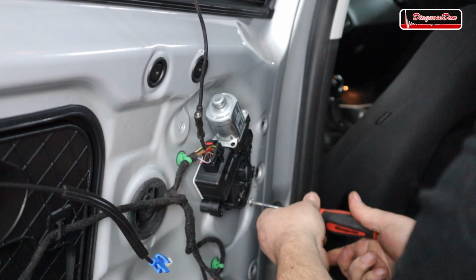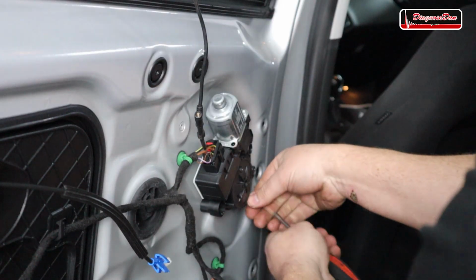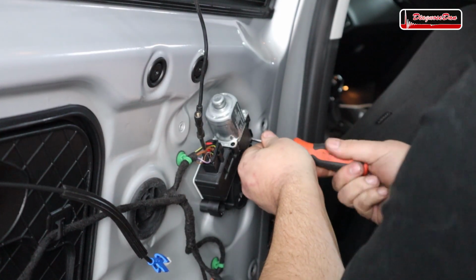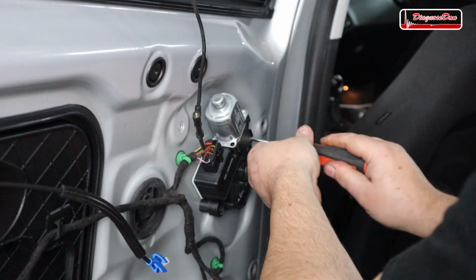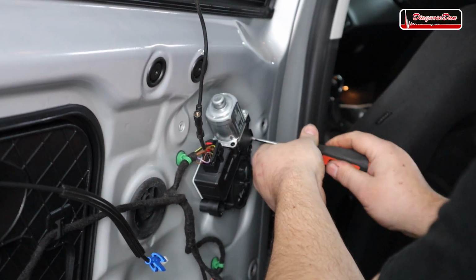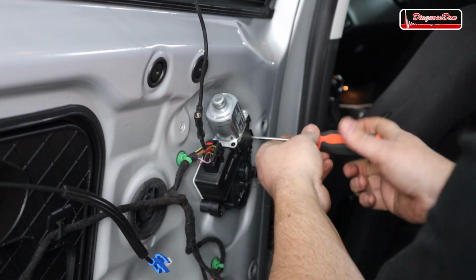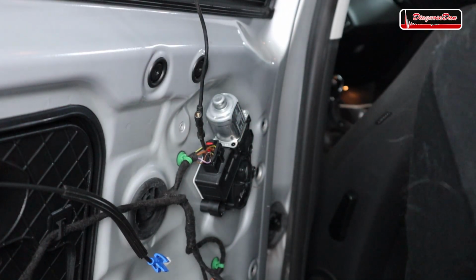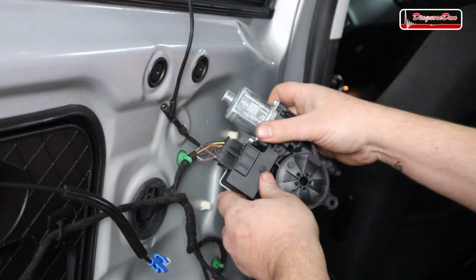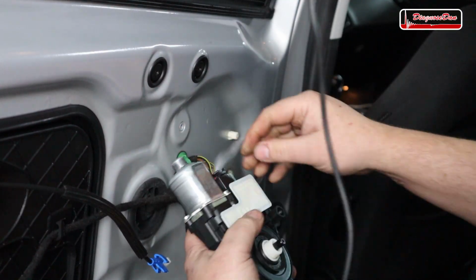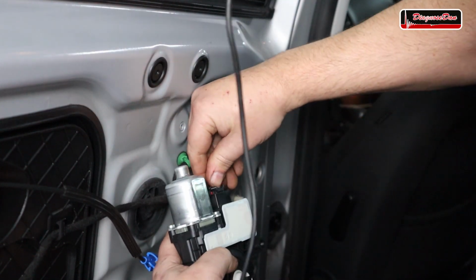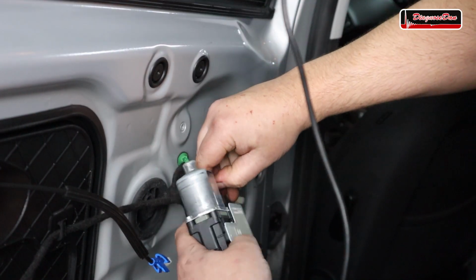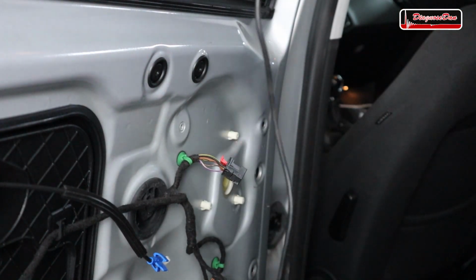That still means we have a problem, because obviously this wire is still broken. That wire runs all the way from the front through the vehicle, through this door to this module, so obviously it could be broken anywhere. We have already checked this area over here, and it looked like it wasn't broken over there, but it has to be broken somewhere. So in the next step, we need to find out where.